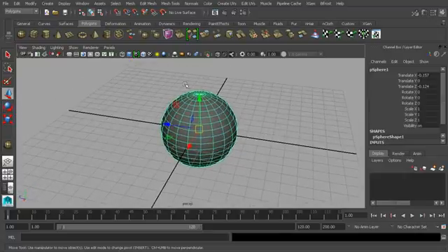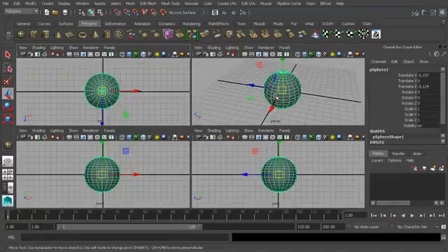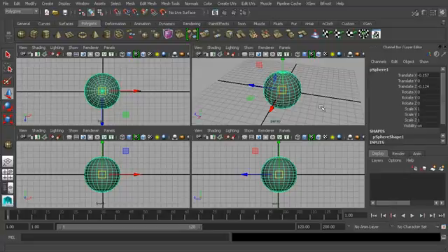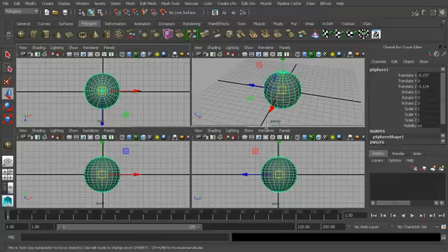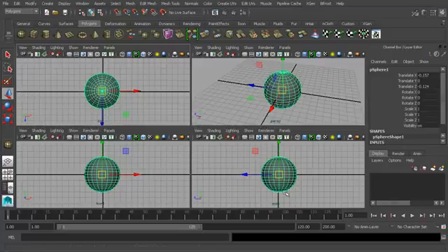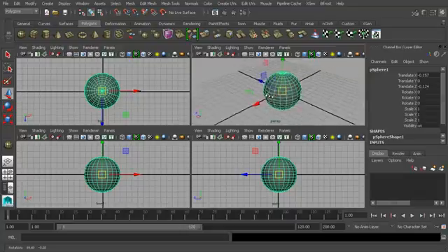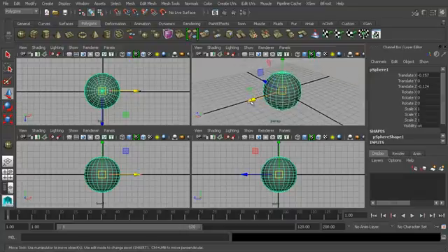If we want to see different views, we can hit the space bar, and that'll take us to our 4 views here. You can see basically this viewport has been duplicated 3 times and put in a 2x2 grid, but the views are different. So this is the top view, so we're looking at the geometry from the top without any perspective. This is from the front, and this is from the side. And you can see the axis difference here. In this case, this is the positive X, so you can relate that to this direction in the perspective view.